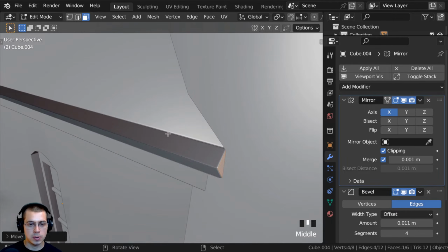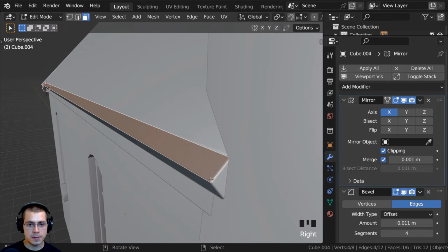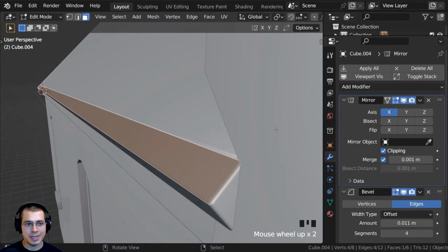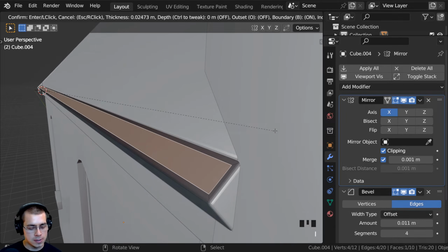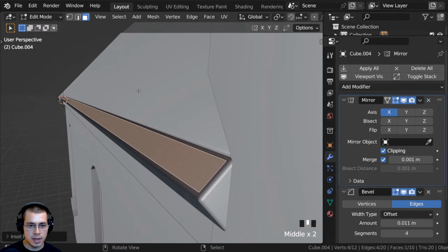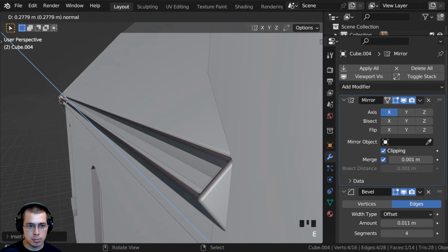And then I want to extrude this part in here so that there's actually a place for the water to go in the gutter. So select this really long face here on the top, and you can press the I key to inset the face, and then it's really sensitive, so if you hold down the Shift key, that'll make your movements less sensitive, so I can drag this around, and I'll just stick it there, and then I'll hit E to extrude, and I will bring that down, and I'll bring it back inside there.